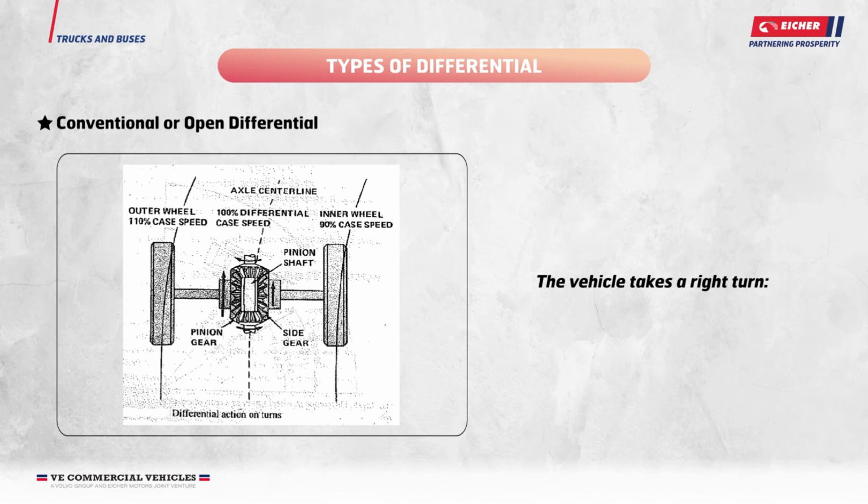The effect of the combined rotation on the side gear is interesting. When properly meshed, the side gear has to have the same peripheral velocity as the spider gear. Technically speaking, both gears should have the same pitch line velocity.